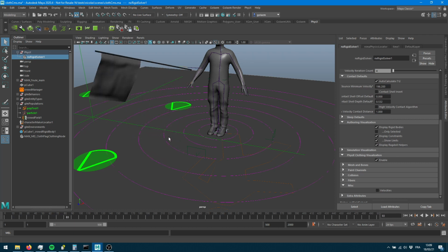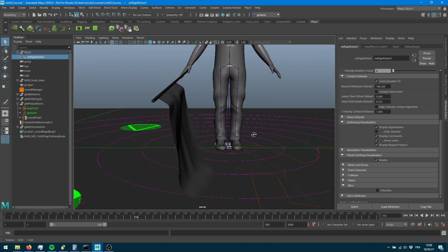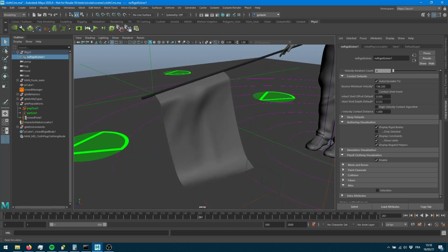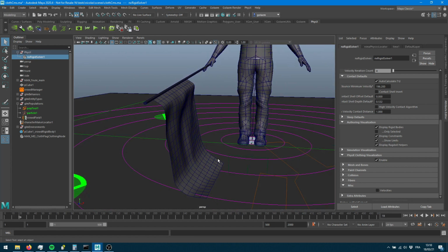Okay, and it looks okay, but for some reason I would expect my cloth to move more; I can feel it's kind of stuck in some situations. The vertices at the bottom of my flag feel limited, and you can see when I run the first frame, let's add some wireframe on it, I can kind of feel my vertices are blocked. Also, as a side note, I haven't painted any max distance onto those, so they are considered constrained, and the skinning is what controls them. So my issue here is that my vertices seem limited.